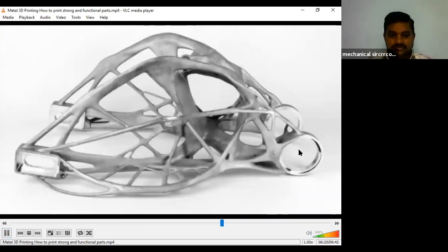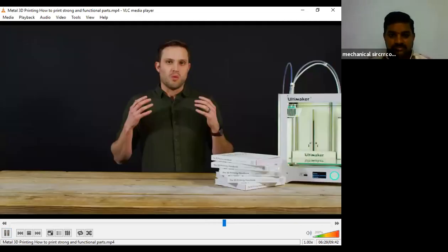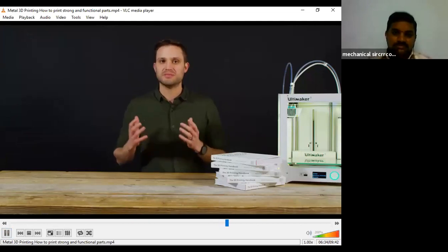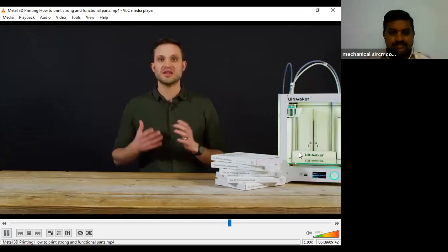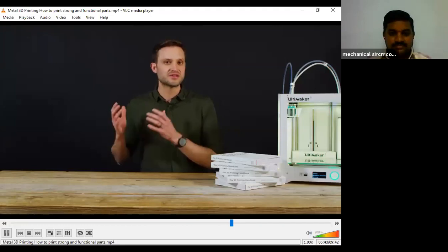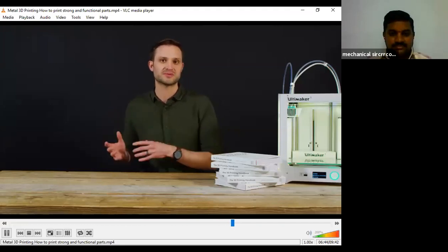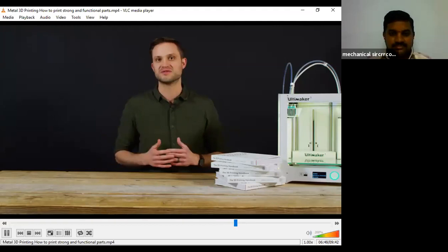Optimization and generative design are also perfect to utilize with metal 3D printing. One important thing to keep in mind is whether all parts of your design actually need to be metal 3D printed. Often, it's better to choose a traditional manufacturing technology like CNC for some of the more basic sections and then use 3D printing for the complex parts, assembling these all together at the end. This can save a lot on the overall cost of your design.